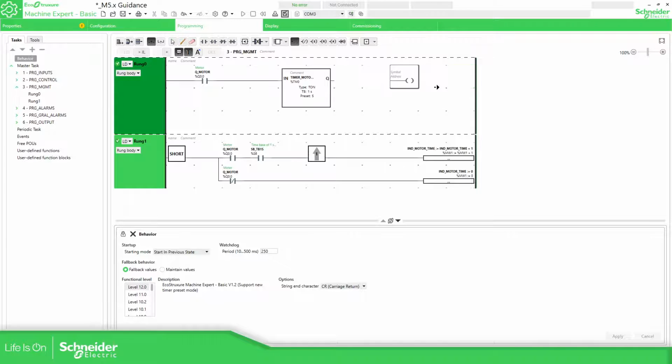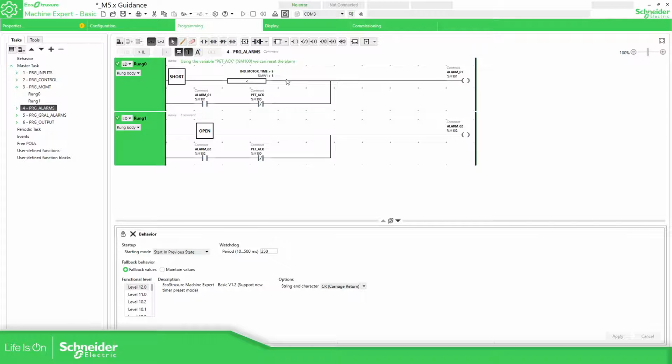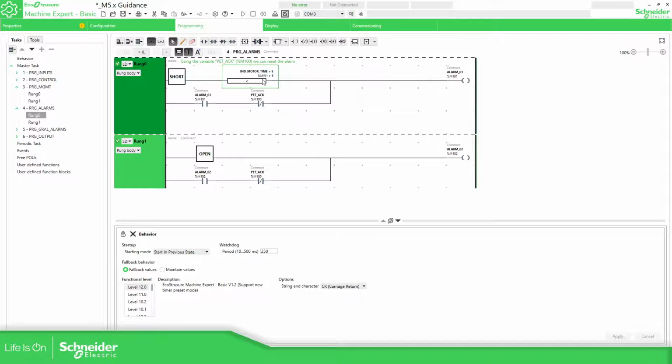You can easily use another variable, okay, and here select the %M that you want, but I'm going to make the things a little bit different so we can use the output directly of the block where we want to do it. So here I'm going to replace this. I'm going to add the contact here, %TM0.Q, because it's the timer on that we have selected the output. So it's the same as using a %M, but I'm going to use directly the output. Now let's go back to the presentation to see if I'm missing something.